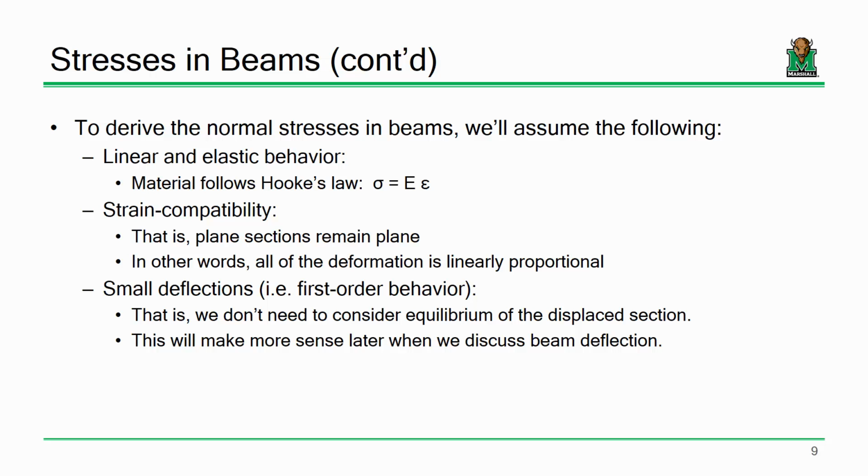One of the at least readily direct applications that we'll need to consider is lateral flange bending. It's a particular type of twisting that occurs in beams like bridge elements when they're twisted. And a simple example of a bridge beam being twisted is during concrete deck placement, because you have your overhang forms on the exterior girders and they want to twist those exterior girders. So we'll need to consider the large deflection aspect, and we'll talk about what that means later.